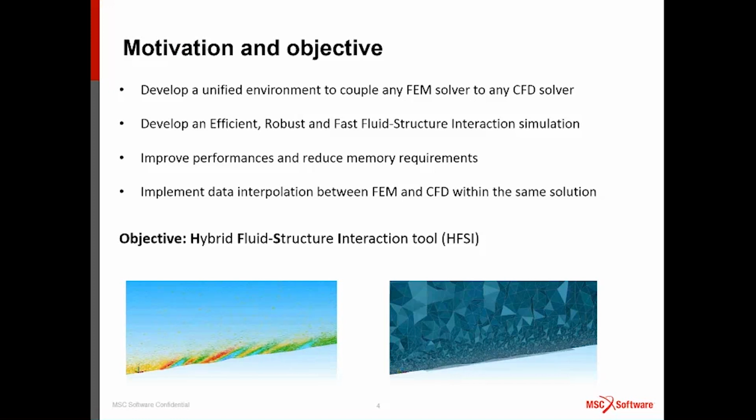thought about developing a unified environment able to couple any FEM solver to any CFD solver, so to have something that is really flexible. We also wanted to develop something efficient, robust, and fast in order to perform an efficient fluid structure interaction simulation. For this reason we have worked a lot on performance and on reducing memory requirements, and for this we have put in place something really cool in which we have used Nastran to do a lot of stuff.